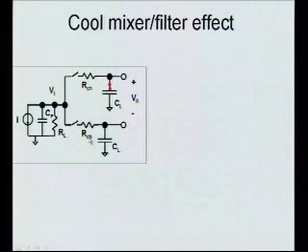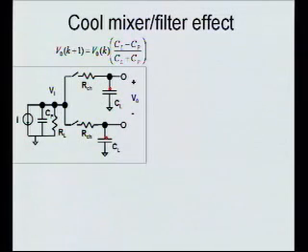All right, I'm just going to talk a little bit now, with my little chargers again, to reiterate what I just said. Say we started out with a situation where the output voltage is fairly large, so all the charge is concentrated on one side of this differential pair of capacitors. Now when I do the switching, it does that. Charge gets transferred across. Also, my LNA has some inherent output resistance, some real part. So if I just define mathematically what that does, from one cycle of LO to the next cycle, that's what the K is: the charge of the output will decrease by this ratio.